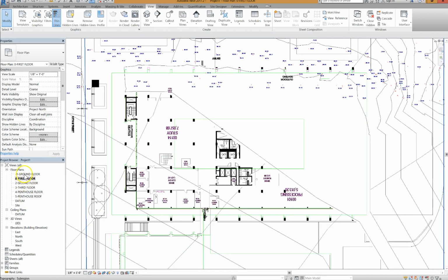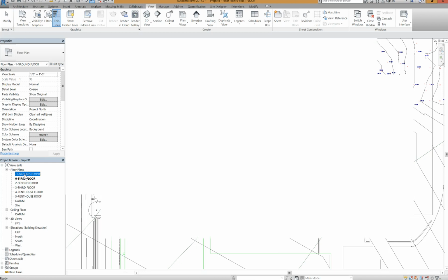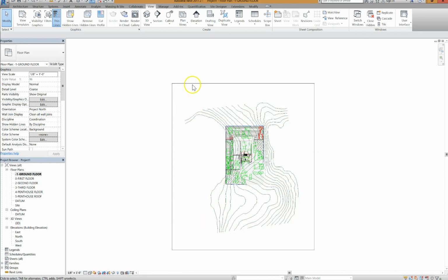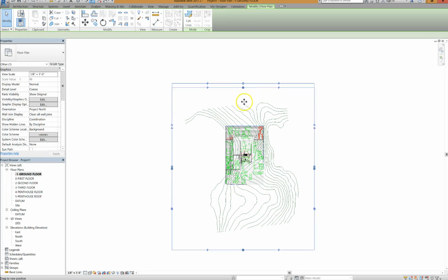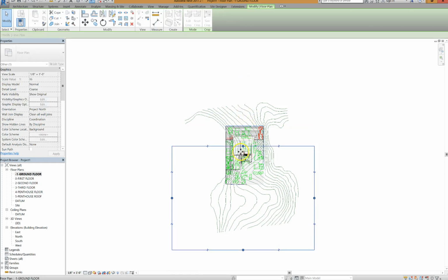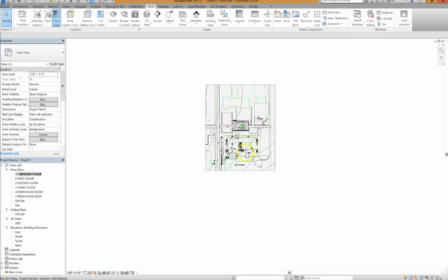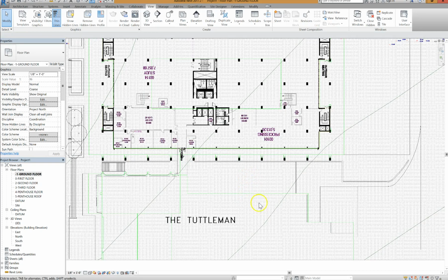So what I'll probably do is actually go down to the ground floor and put the building pad in, just to cut a deep hole. I do need to crop all these views down, of course, so that we're not showing the entire temple campus for each floor plan. But this is just how you get going with the Revit file. Crop. Alright.